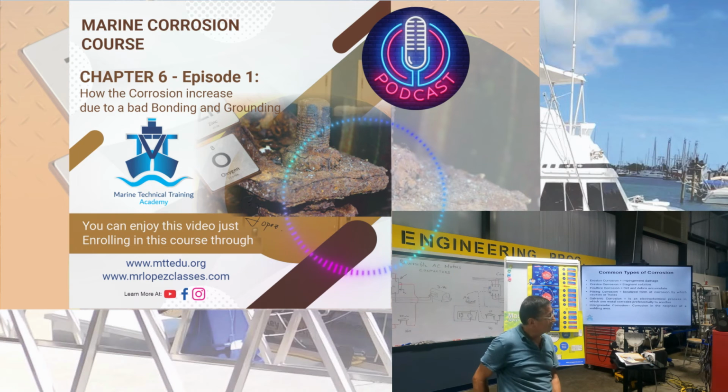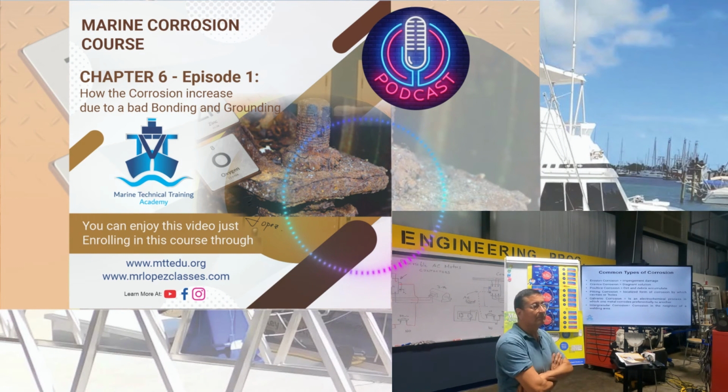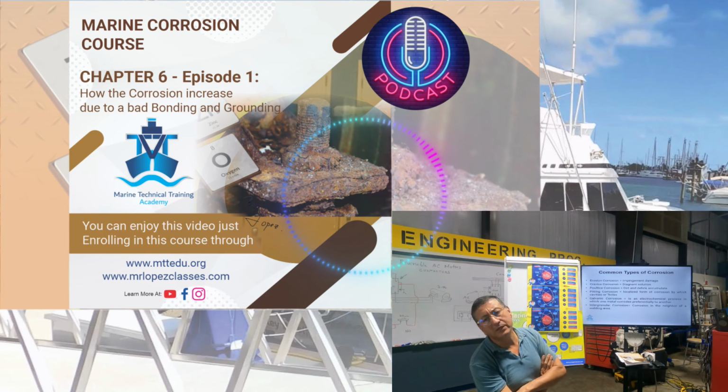The ground that is coming from the shore power entering the boat. If the ground coming from the shore power is contaminated with noise or interference, it enters the boat and creates corrosion and oxidation and damages all the metallic elements inside of the boat. For that reason, the recommendation is to insert the galvanic isolator in series in the ground line.